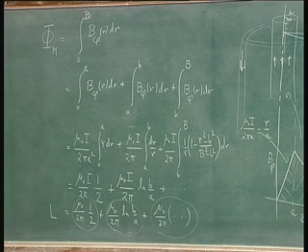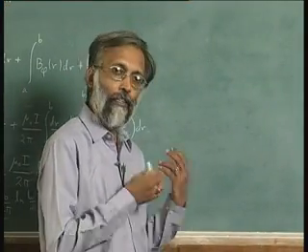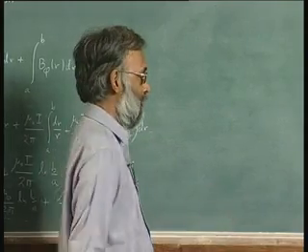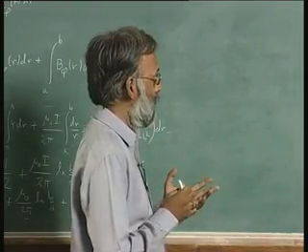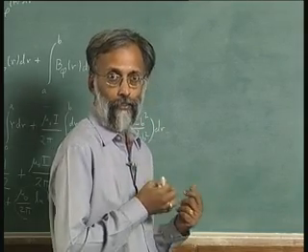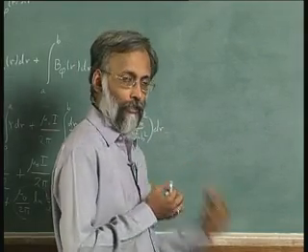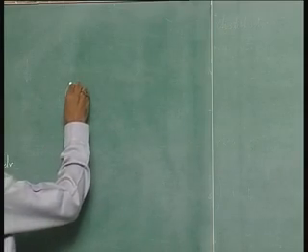So, we have talked about two kinds of inductances: external inductance, or the normal kind of inductance, and internal inductance, which is the inductance due to the fields within the wire or within the conductors themselves. The important thing to remember with internal inductance is that it is always present, and in fact it is a good thing that it is present, because supposing you think of a coil, a loop.